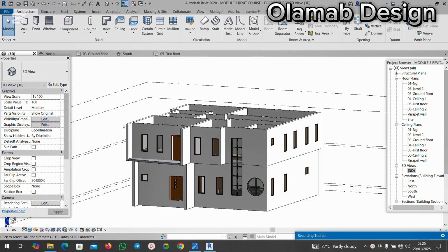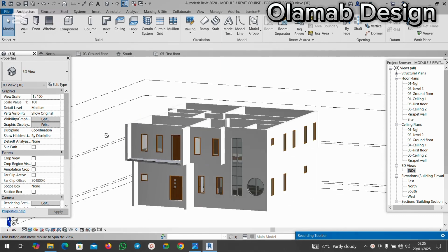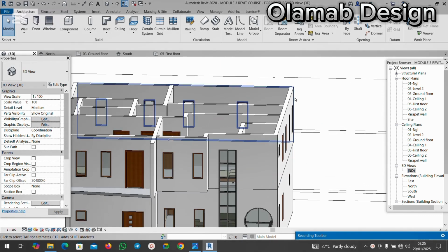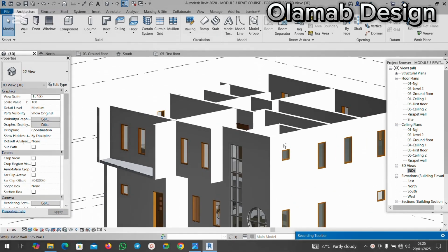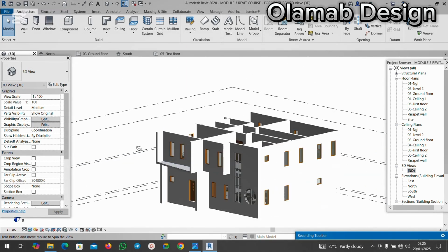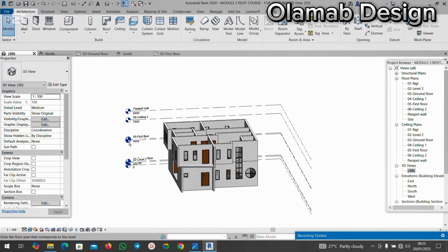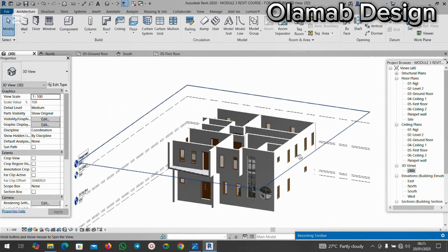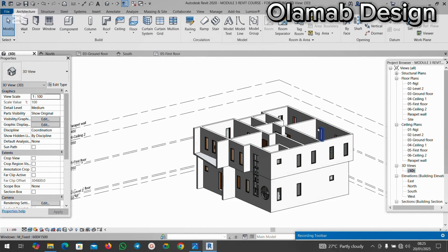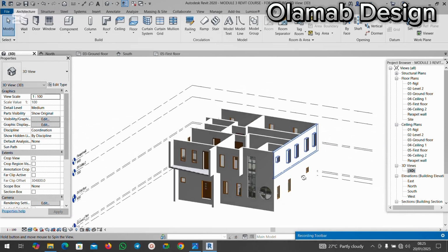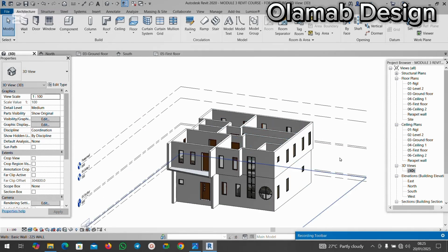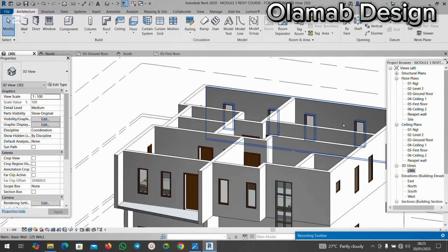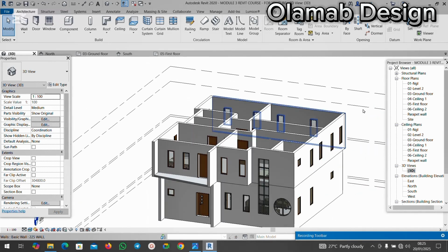Whenever I'm creating a roof gutter, I always like to consider a straight wall, whereby there can be a pipe inside the wall that will take the water straight down. So where I don't have a recess at all, like this place now, you can see that there is a recess at this point. So it's either I slope my roof towards the left, the rear elevation of the building, or I slope it towards this side. To do that, I will go to create my parapet wall now.